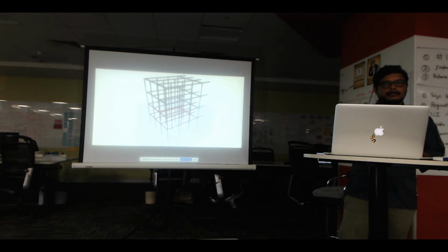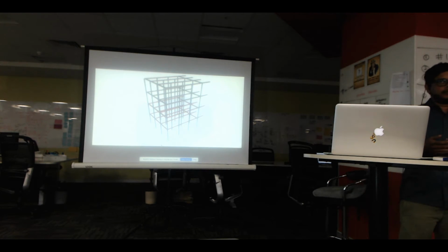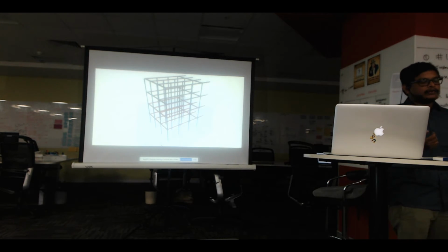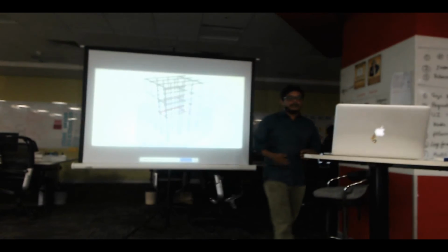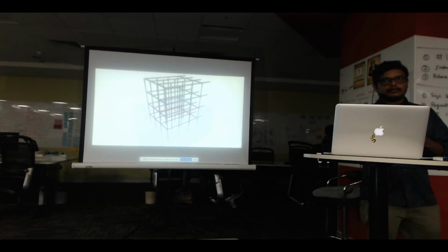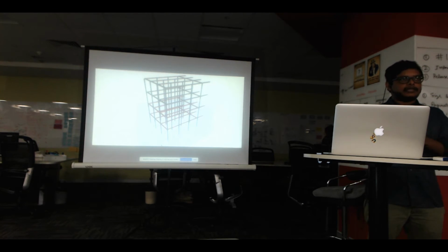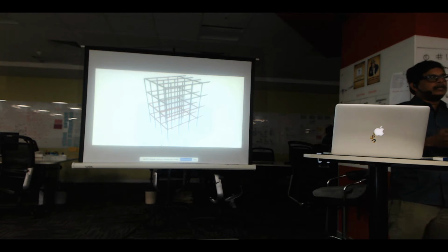The second one is not so big a problem to solve, but if you look at the circuit, we have 64 LEDs which can get lit up at the same point of time, as many as in one layer, right? So the amount of current that you will need to source to get all of them lit up would be pretty high, which, if you connect it directly to the microcontroller, will damage the microcontroller.